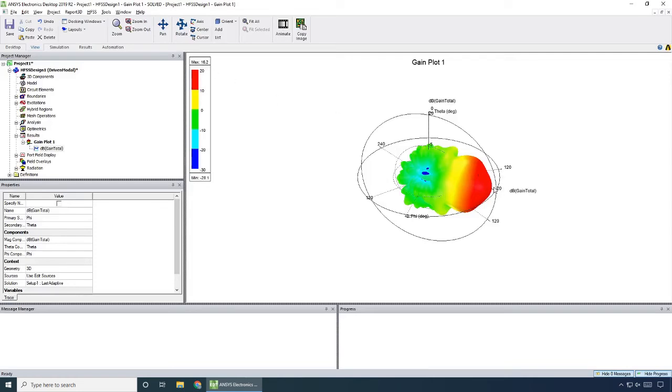actually we can convert that into a ratio that tells us how much stronger it is than a normal antenna, or an antenna that is equal in all directions. So in order to do that, you divide the 16 by 10, and then you raise 10 to that power. And so that's going to give us a relative increase of about 40 times more powerful.